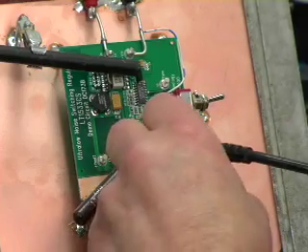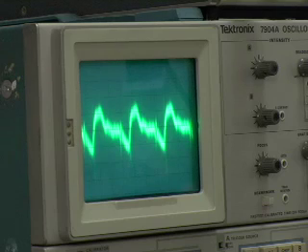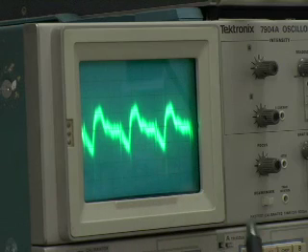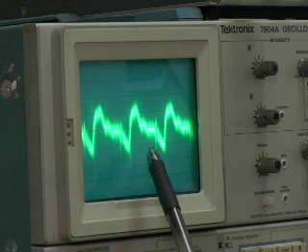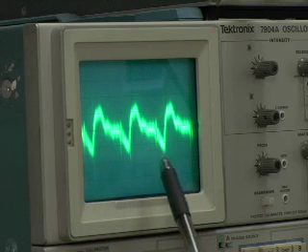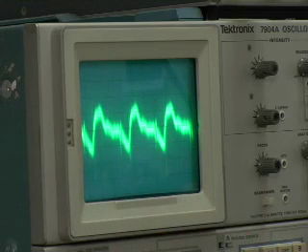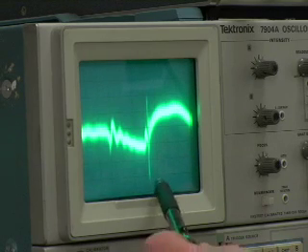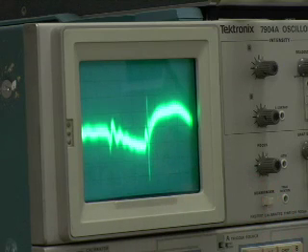Now let's move the signal channel from probe ground to signal. The ripple that we talked about earlier in the presentation becomes clearly delineated. You can see at 100 microvolts per division, we're about 200 or 300 microvolts high. It's harder to see these wideband harmonics, which define the high frequency content in the waveform. If I go to a faster sweep speed, they become clear. This is about 500 microvolts of wideband harmonic, again in a 100 megahertz bandpass.